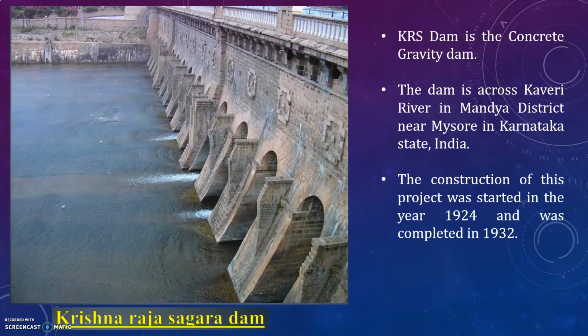If mechanized plants such as manufacturing and transporting mass concrete, curing of concrete, etc. are not available, a gravity dam may take more time to construct. Gravity dams require skilled labor or mechanized plants for its construction. It is very difficult to allow subsequent rise in the height of a gravity dam unless specific provisions have been made in the initial design. These are some of the advantages and disadvantages of gravity dams.